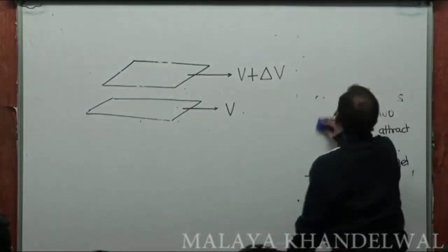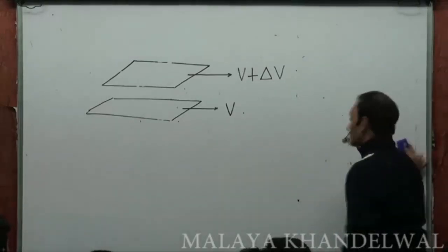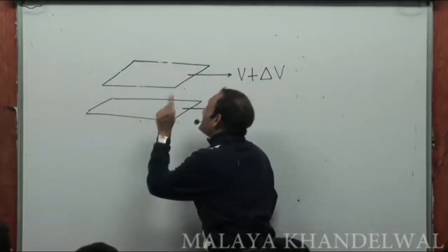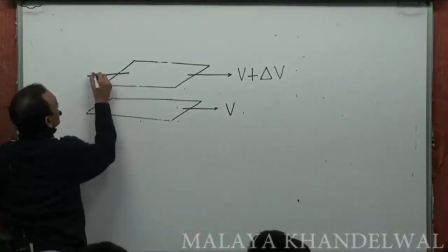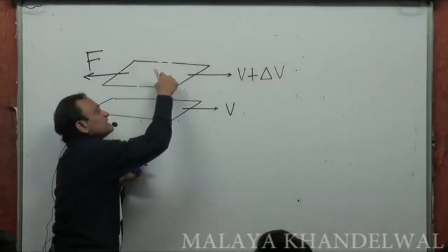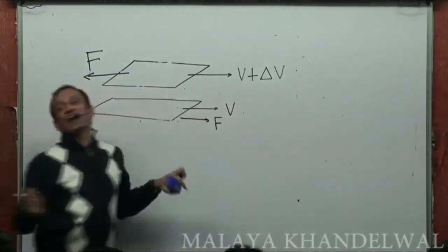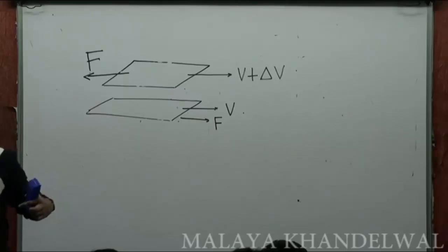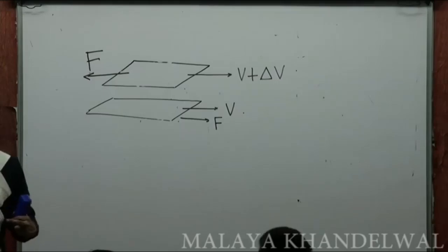Now, let us understand the model that supports viscosity, the mathematical model that supports viscosity. So, because of viscous motion, because of viscosity, this layer would exert on this layer a net force like this, a tangential force like this, and as a consequence of reaction to this force, this layer will exert on this layer a force equal and opposite drag like this, which is called a viscous drag. It opposes not motion but opposes relative motion, just like friction, right? It opposes relative motion.